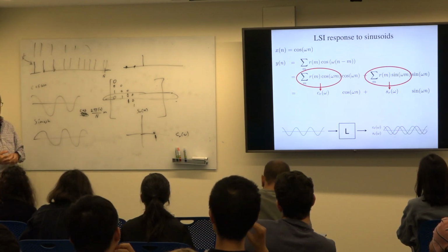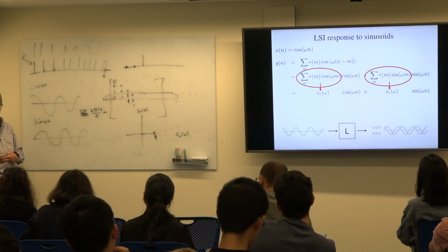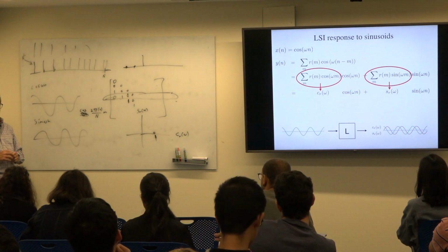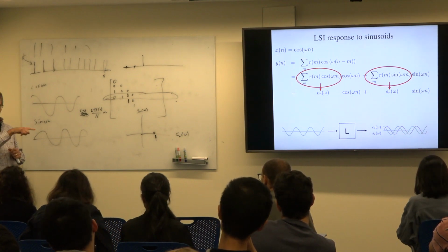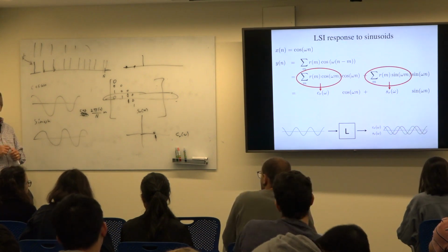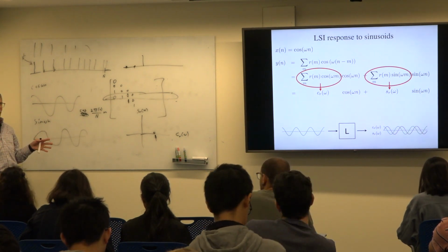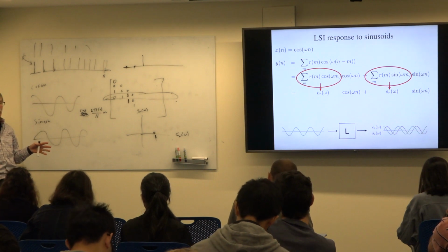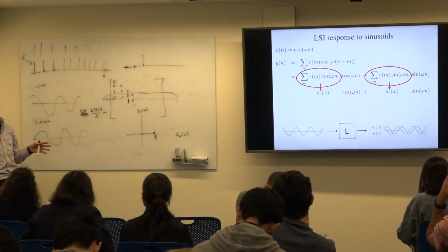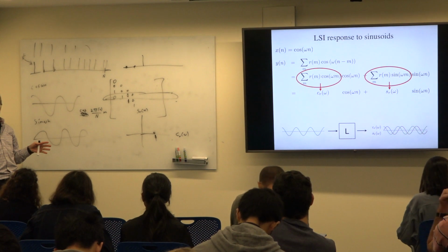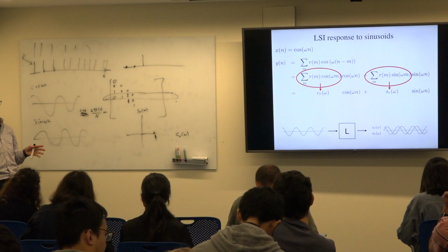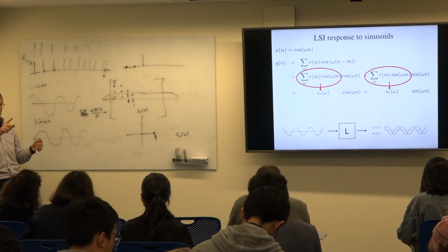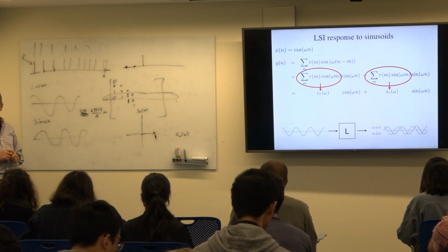Okay? So when you give this thing an input, if it has any frequency whatsoever, it's thrown away. It's gone. However, if it has some input that's not wiggling, meaning if your input signal has an average that's non-zero, that average will be output, always, at all times. So it's taking the constant function that you've given it, and it's preserving that, and it's taking any modulation of that function and throwing it away.